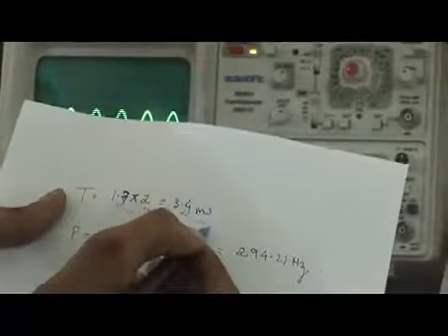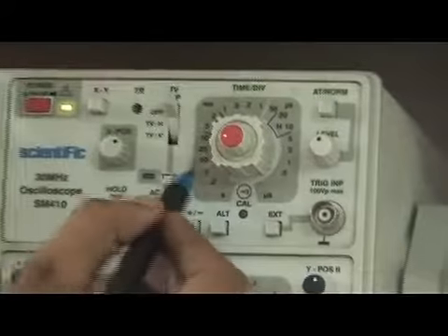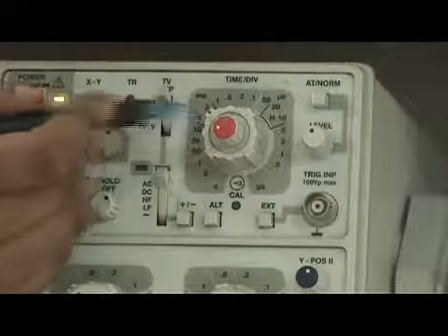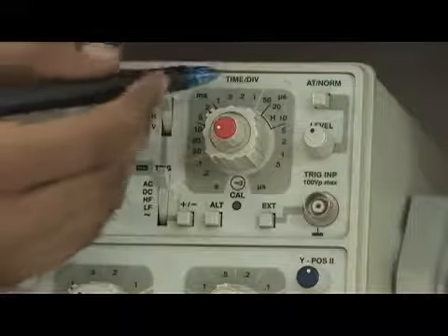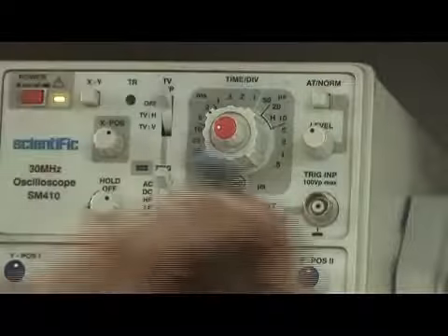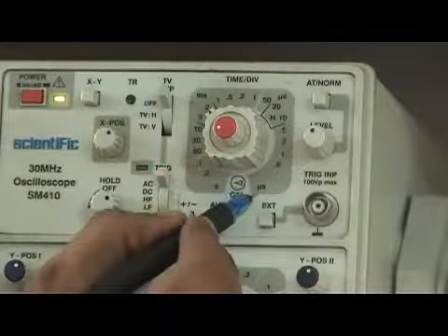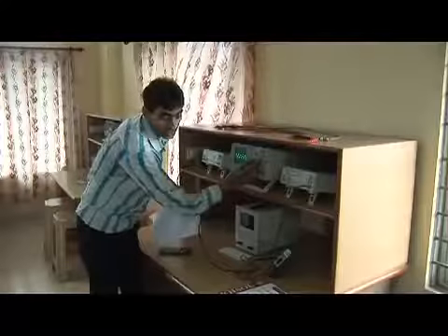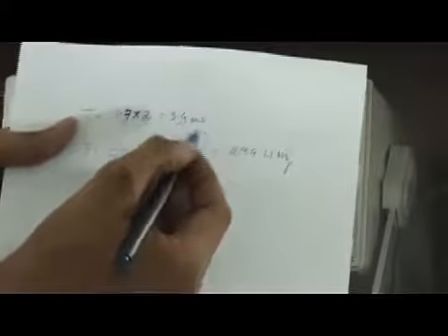Why have I taken milliseconds? Because from this gap, from here till this gap, there is a small line. The unit will be in seconds if this knob is somewhere here. From here till this gap, the unit will be millisecond if the knob is in this range. From this gap till this gap, if the knob is over here, then the unit will be microsecond. So we have three different units on this scale: seconds, milliseconds and microseconds. As my knob here was in the millisecond range, I have used the unit millisecond.